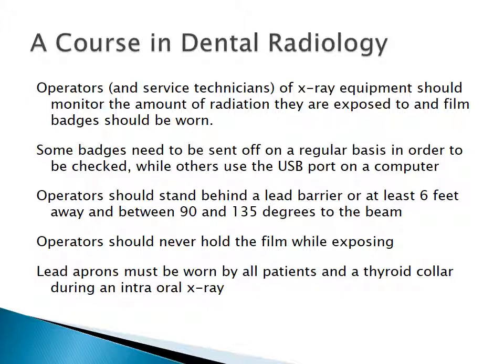The important thing to remember is that the operators of X-ray equipment, and you as a technician, should monitor the amount of radiation that you're exposed to. So if you're going to be dealing with a lot of X-rays, we recommend that you wear what's called a film badge. Some of these badges need to be mailed back to the vendor that created them, and the other ones you simply plug into a USB port and they tell you what's going on.